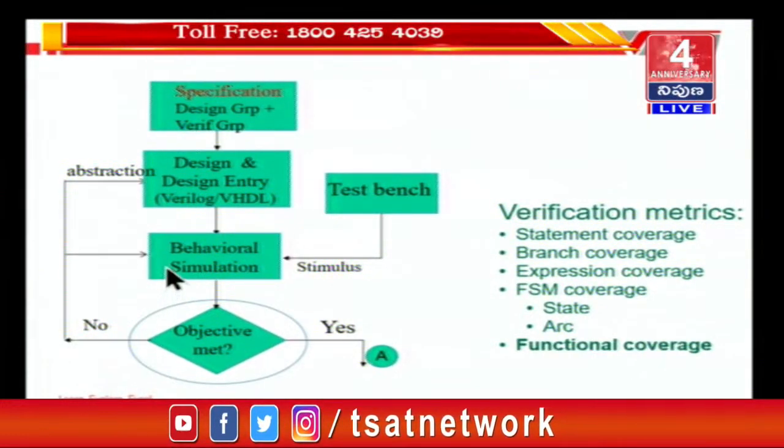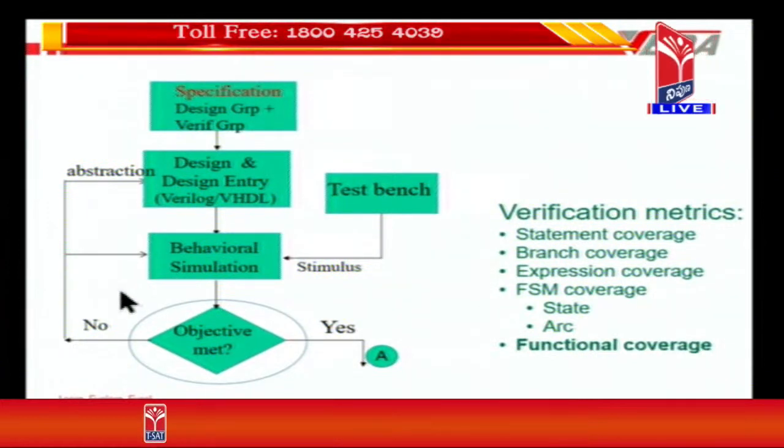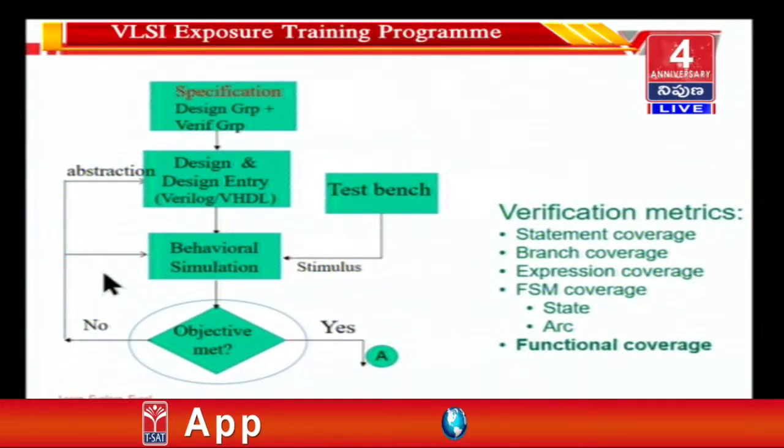Sometimes what happens is this: you decide to manufacture a chip, and later when place and route is being done, it is found that the area which has been decided before by the management, because management decides the area as that determines the cost, is not enough to do place and route.